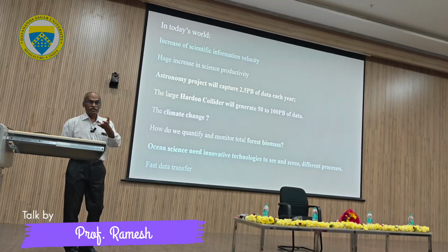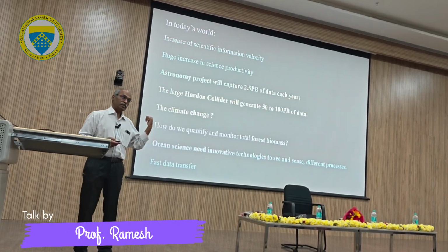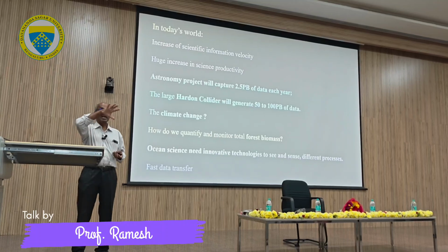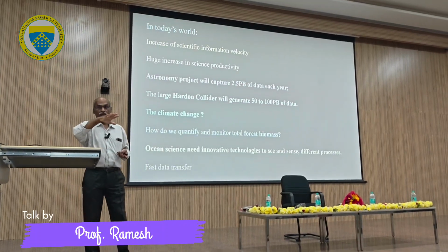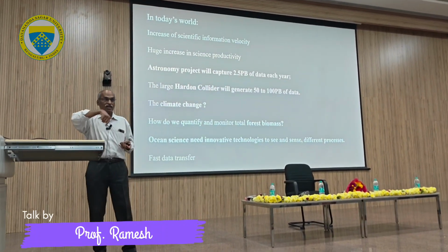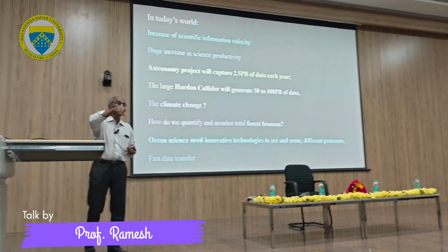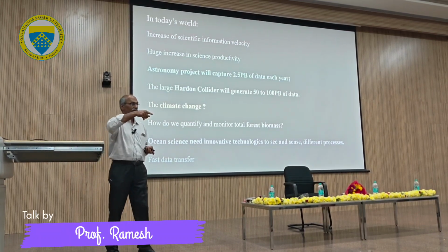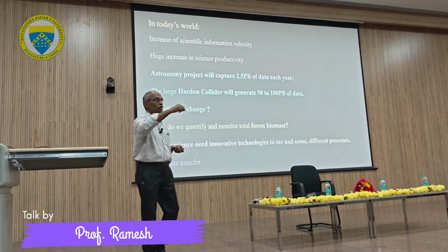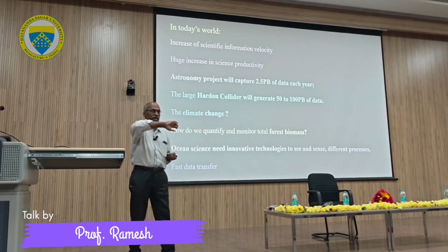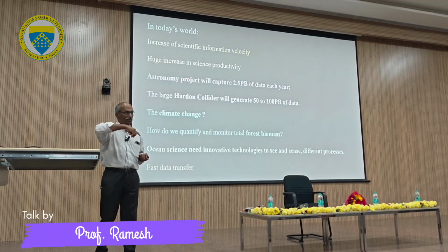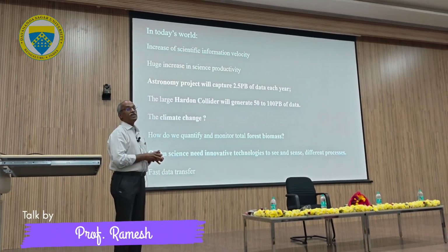For example, your CDs or DVDs are all made of chalcogenide glasses. CDs you must have seen, right? If you buy a new CD, you can see it's very shiny. It's a crystalline state, right? Very shiny. After writing, you see the portion is very dull because it has transformed to the amorphous state, so its reflectivity is very low. So when you send a read pulse laser, it sees the reflectivity difference between these two states and gives the corresponding information.